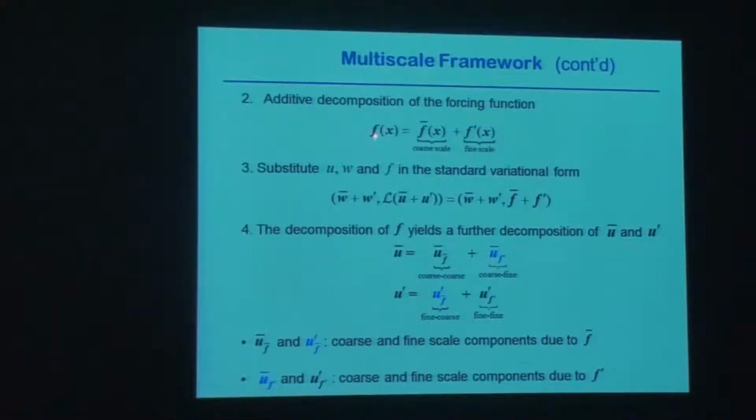Now, this additive decomposition of the force f into coarse and fine scales will lead to a further decomposition of the coarse scales into a part of the coarse scale displacement that is induced because of the coarse scale forcing function, and a part of the coarse scale displacement field that is induced because of the fine scale forcing function. And likewise, the fine scale displacement field has a component coming from the coarse scale force and the fine scale force.